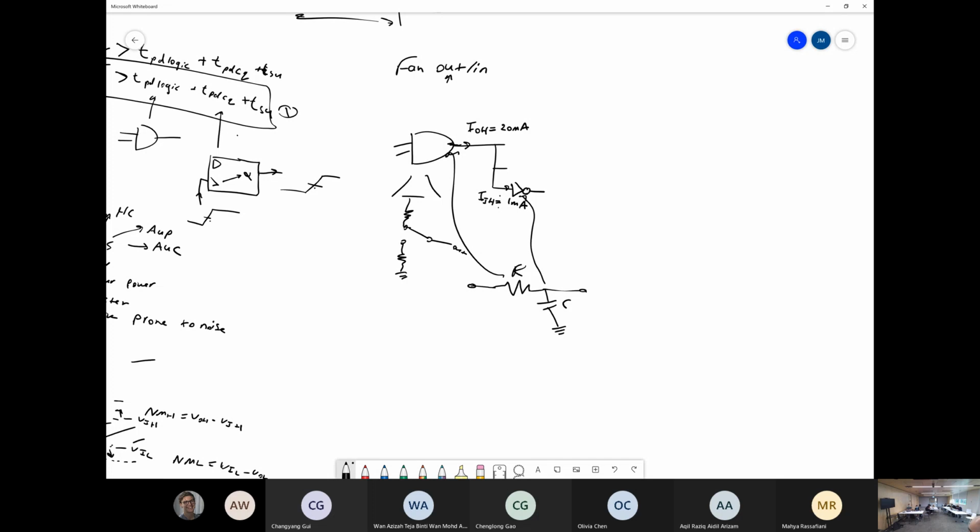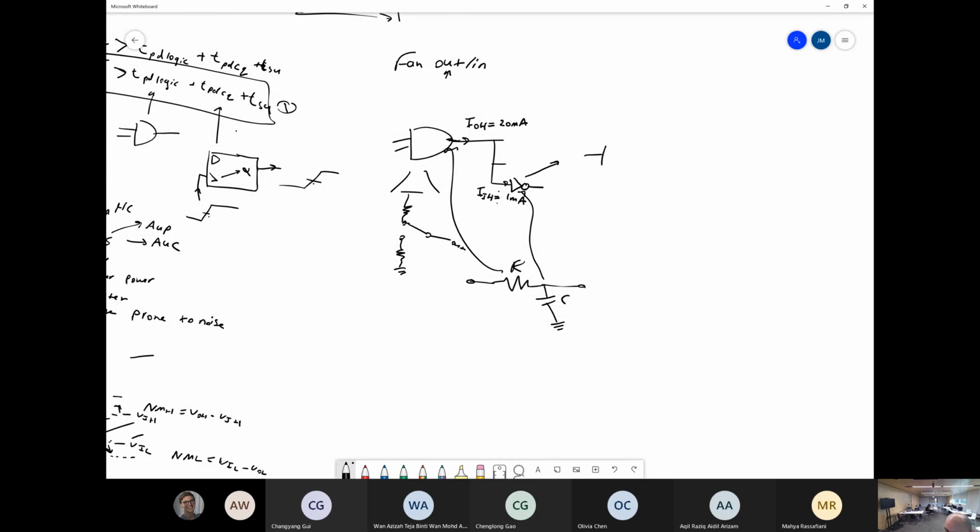Let's just say this is a CMOS gate, right? So looking into here, you'll have a CMOS inverter, which looks like that, tied together, right? The equivalent circuit, if you look into a MOSFET here, just looks like a capacitor. And so these will combine in parallel. So you'll have some sort of equivalent capacitance, again, out of the scope, but that's where this capacitance down here comes from. And you'll have this internal resistance, which is where this internal resistor comes from.